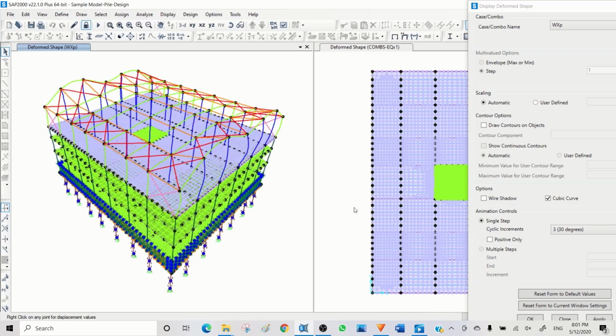So you can just check the maximum and check the story drift. You need to ensure your lateral stiffness is sufficient. If you see the drift is too much, or if you see some unexpected deflection, for serviceability purposes, you need to change the size of the element.